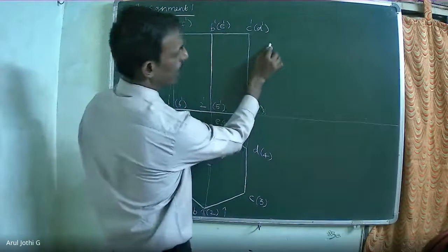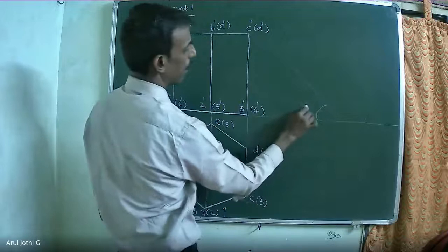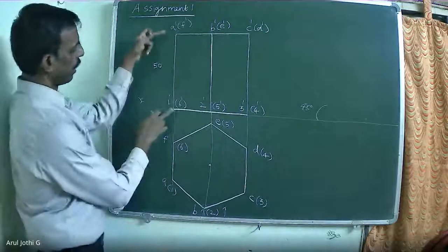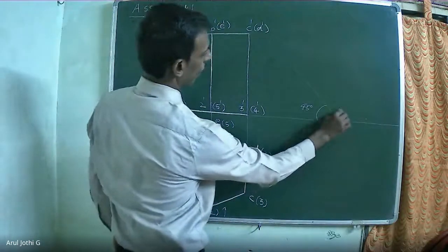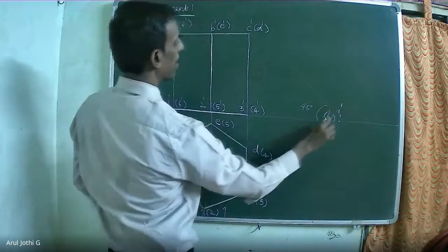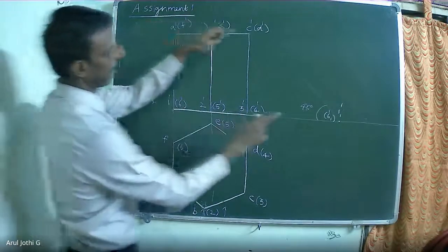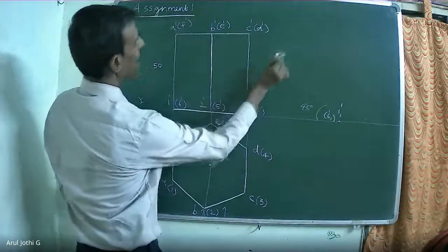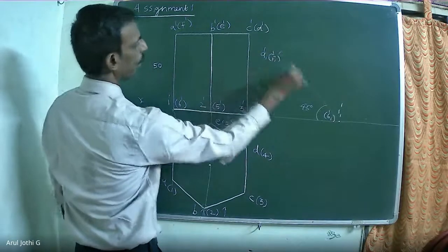So the given angle is axis inclined at 45 degree to HP. Draw one 45 degree construction line. Now measure A to 1 and transfer on this line. So here corner 1 will be available and 6 will be available. So measure the vertical height, that is equal to 50 mm, and transfer on this construction line. So this will be A1 and F1.